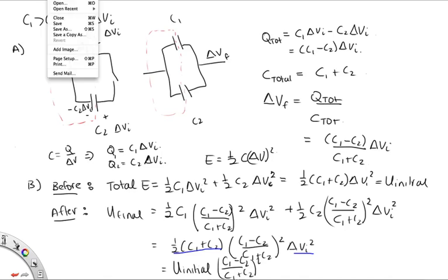One more example. This example was in the 2010 1231 paper. Suppose you have two 3000 farad capacitors. So C is equal to 3000 farads. And we have a battery with a voltage difference of 120 volts across it. Part A of the question says calculate the total energy stored in both capacitors if they are connected in series across the battery. Draw a schematic diagram showing how the capacitors are connected to the battery.